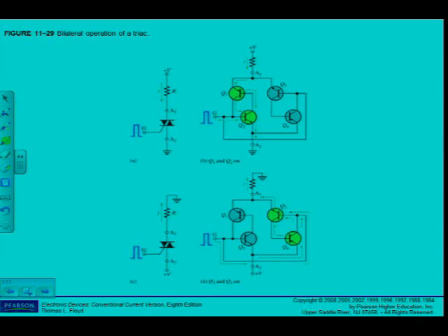The transistor equivalent circuit in part B shows that Q1 and Q2 conduct when a positive trigger pulse is applied. In part C, terminal A2 is biased positive with respect to A1, so that the triac conducts as shown. In this case, Q3 and Q4 conduct as indicated in part D upon the application of the positive trigger pulse.